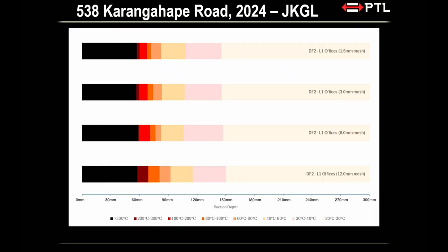So you will see during that particular fire that was imposed, we have about 60 mil of charring. All right, all this color along here. For the next probably 90 mil is when you get to 20 to 30 degrees Celsius. That's your 20, 30 degrees Celsius range. Right? So if you say, look, I'm going to discount everything 100 degrees and beyond, so I'll discount 100, 200, and 300, not going to use that for my loading calculation, then you're probably looking at this particular line here.